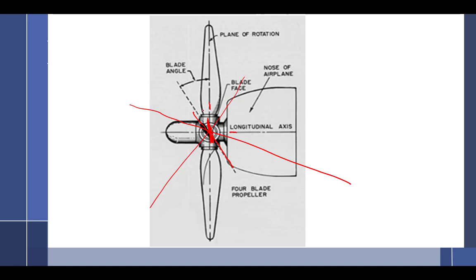Okay, the same, so you have to remember that's what's going on here, and that's what I'm talking about. Not only does this happen in flight, but if you're measuring the blade angles, it's going to happen even on a static. You take a propeller, put it perfectly horizontal, but the aircraft is tilted, and one blade is going to look like it's got a lot of angle of attack, and the other blade is going to be no angle of attack.